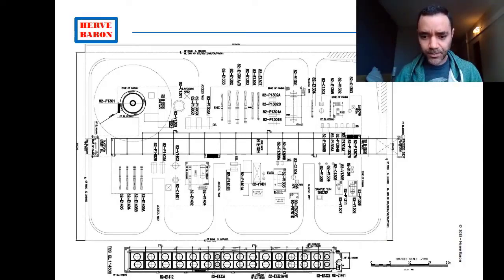So here you have the pump, and you will have a series of equipments that must be cooled down during the process. So let's suppose here it seems we have a batch of heat exchangers. So we have E, so it may be exchangers, heat exchangers. So how will you do the preliminary calculations to define the head of your pump? You will need to get the plot plan.